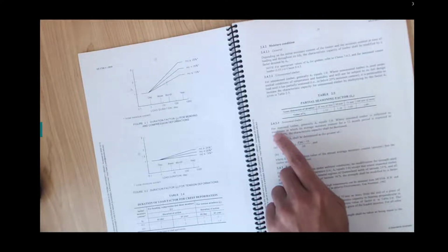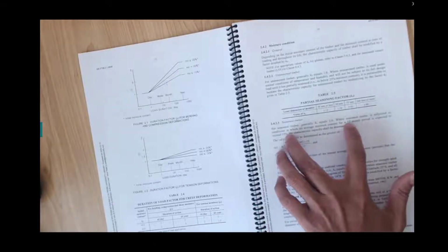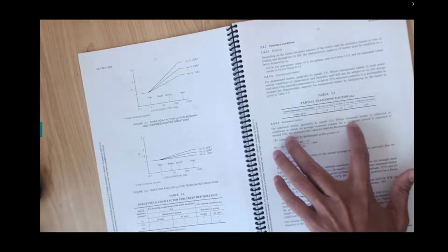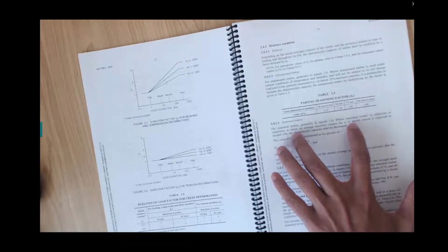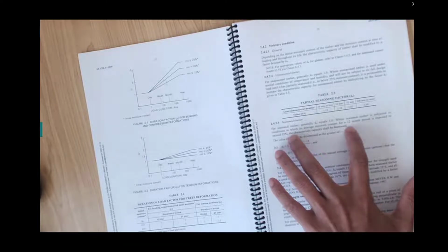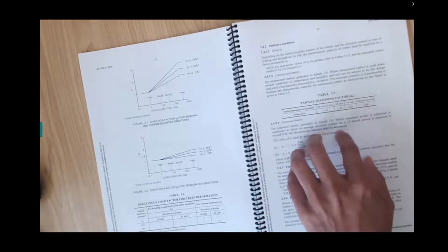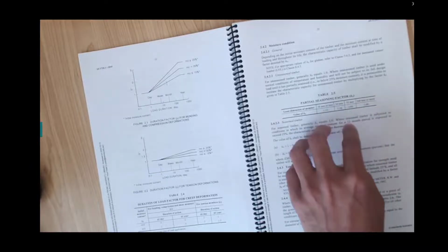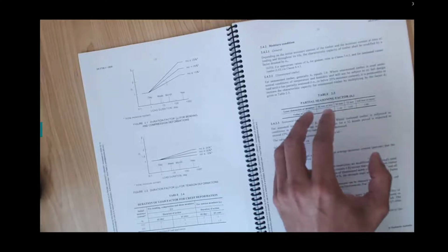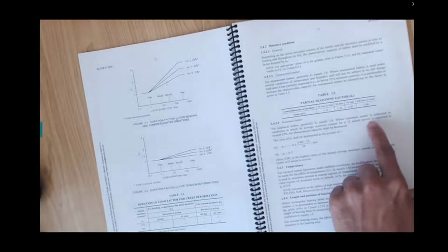Where seasoned timber is subject to a condition in which the average moisture content over a 12-month period is expected to exceed 15%. Your supplier will specify that, as I mentioned, if your timber is exposed to rain and sitting outside of the structure. I think this is a load bearing wall, so it is sitting inside. When the timber goes onto the service, or the column goes onto the service, it has less chance of direct contact with rainwater, or it just has humidity coming from the air. That is not that significant. In that case, your moisture content would not exceed 15%.